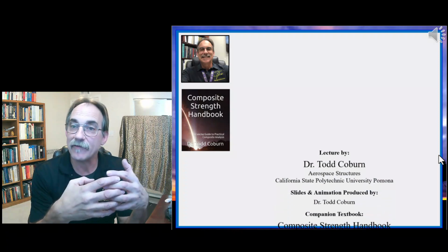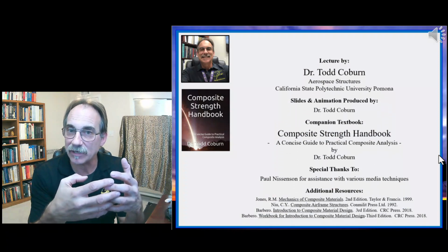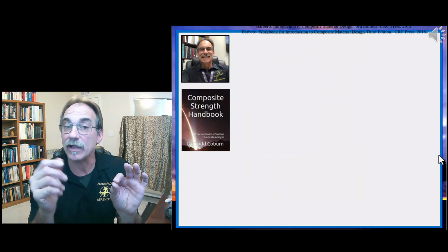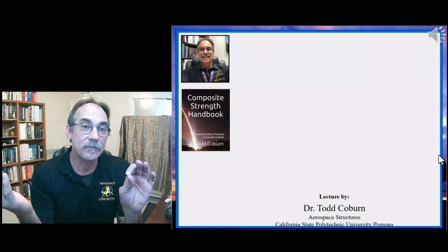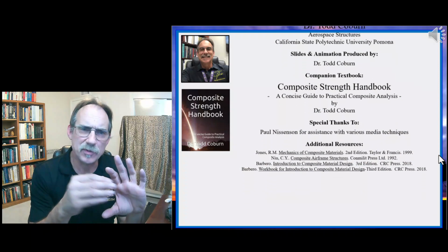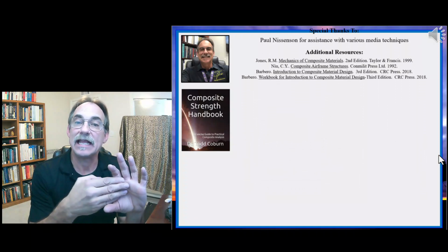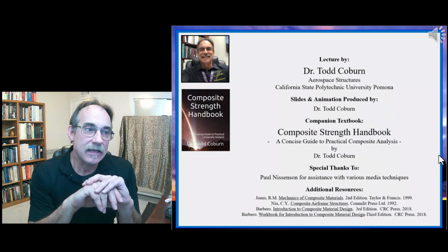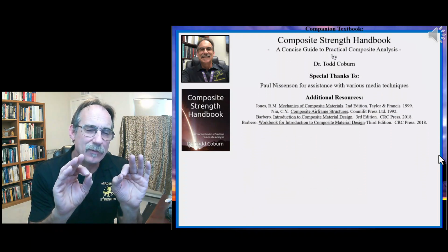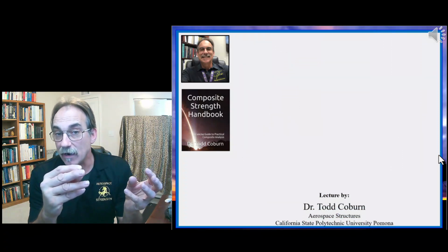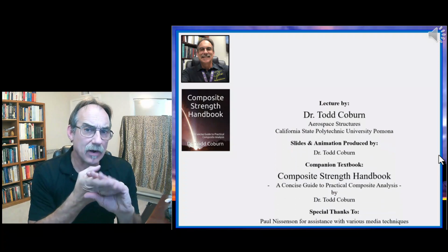Then for deflection, we have our normal bending deflections, which we can get by just using the dB equals EI parameter in our current bending equations. And then we have the shear stiffness, which we haven't dealt with as much, but I gave you a nice easy way to evaluate that for a number of beams. We just sum those together. And then we have some basic ideas on the closeouts and different things we can do there and with design parameters.